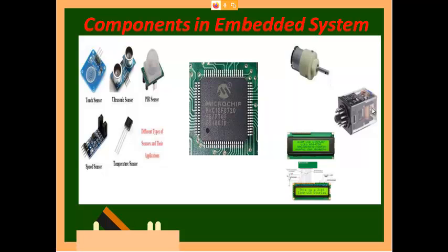In mechanical relays, you don't want any controllers and all. It is all only with respect to mechanical. So that is what was there in your automobile 30 years back. Then what happened is we have moved to electromechanical, where you will have a moving part as well as an electrical part. So you give an electrical signal that will energize a coil, and this coil will try to move a part. So there you have a mechanical part a little bit. You have electronics also. So first one only mechanical, second one is electrical plus mechanical, and nowadays there is no moving part at all. It is totally electronics.